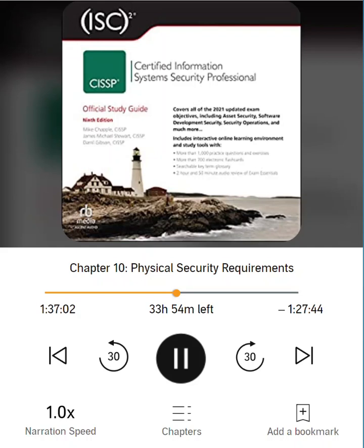sprinkler release occurs. A deluge system is a system that uses larger pipes and therefore delivers a significantly larger volume of water. Also, when one sprinkler head opens, they all open to fully deluge the area with suppressant. Deluge systems are inappropriate for environments that contain electronics and computers. Pre-action systems are the most appropriate water-based systems for environments that house both computers and humans together, because they provide the opportunity to prevent the release of water in the event of a false alarm or false initial trigger.